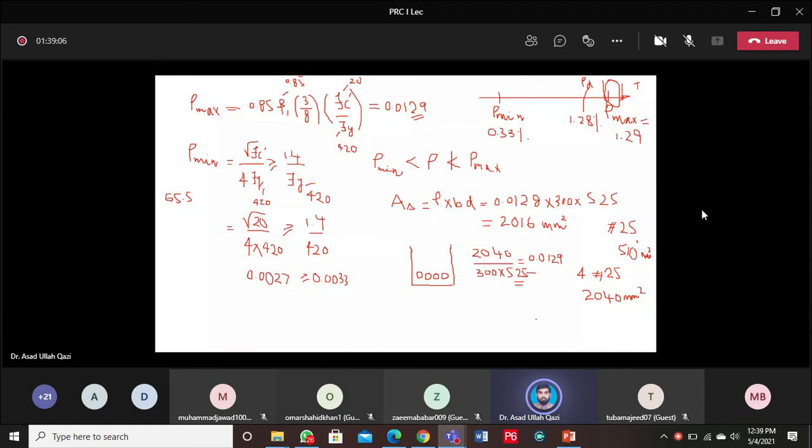So strictly speaking, I may say 600 minus 65.5. So realistically, how much D do I have? 534.5. Sir, 534.5. Good. So in actual, it is very close to 534. So in that way, my rho will further drop, and I am not worried with reference to the actual